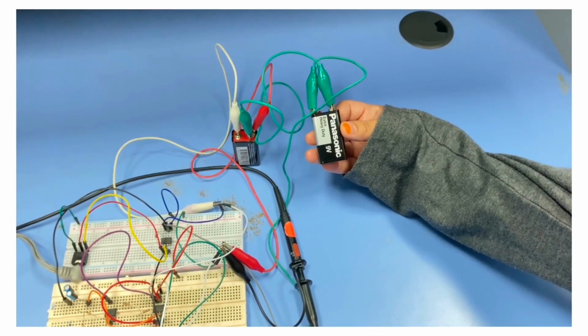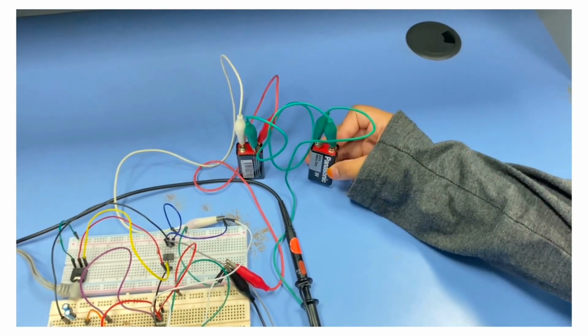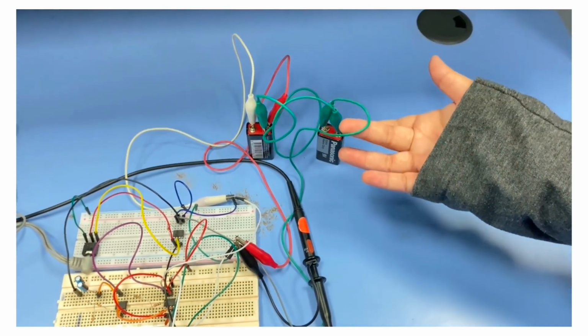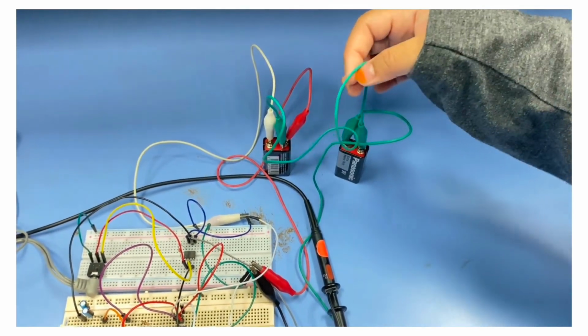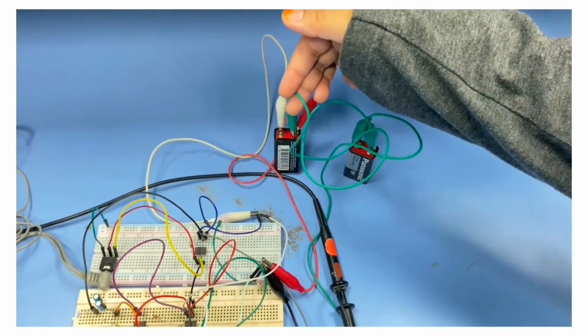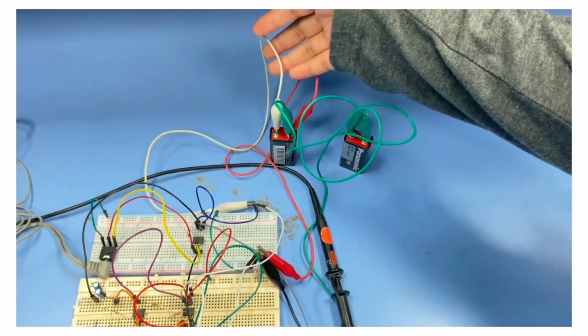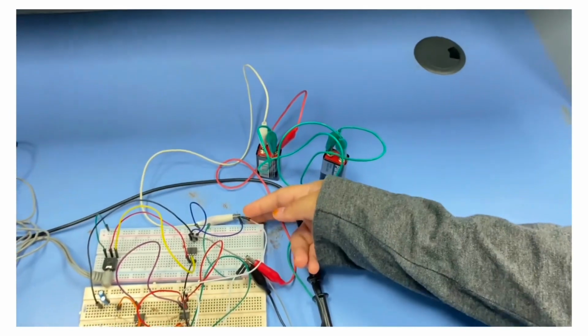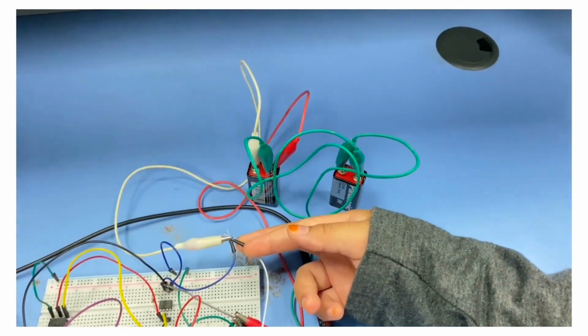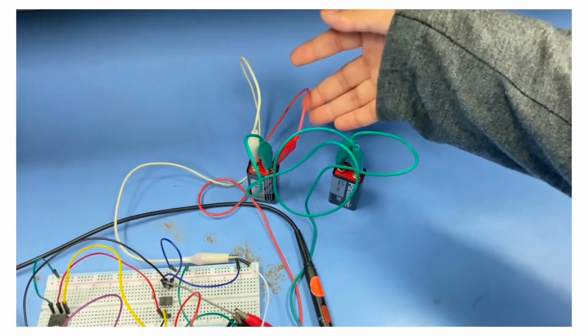In order to measure single channel ECG by using battery as power source, we are using two batteries which consist of 9-volt battery. So first, we have to connect all the crocodile clips to negative and positive batteries. Connect the positive terminal of the battery to the positive power supply pin of each component, and connect the negative terminal of the battery to the ground or common reference of the circuit.